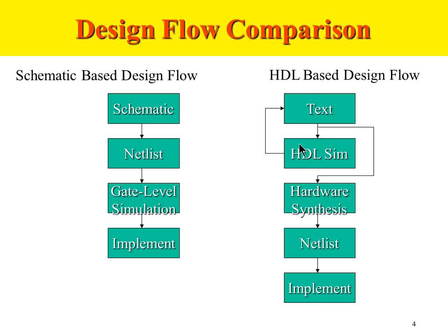If those results have some errors, we go back and fix the errors here itself. So this is an iterative process which goes on till we solve all the functional problems as per the design specifications. Once the functionality is correct in simulation, then we take the design, not the test bench, only the design, to synthesis and backend flow.